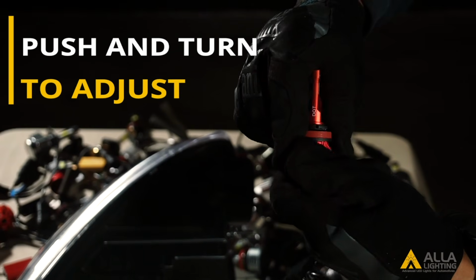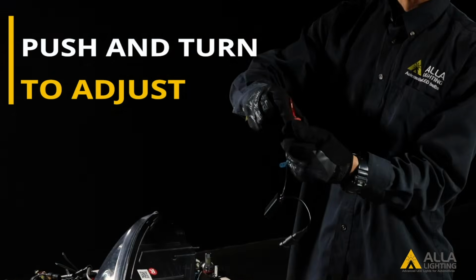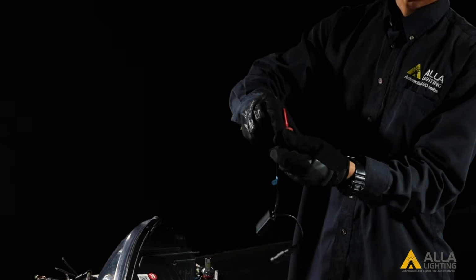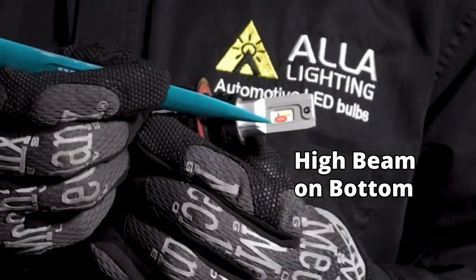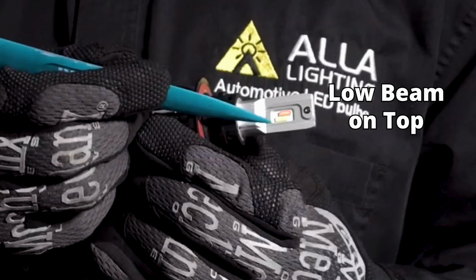Second, check and adjust the beam pattern. There are some cases where you'll get a clear beam pattern that satisfies SAE guidelines right after the LED headlight bulbs have been installed. However, we have seen and installed a lot of vehicles that require multiple beam adjustments. Some even have the high and low beams reversed the first time installed without any adjustments.